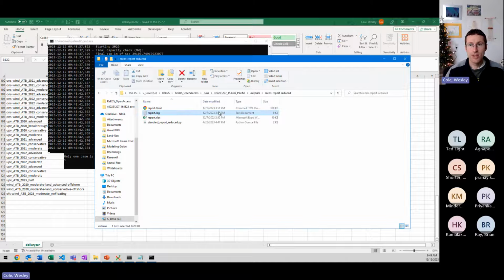Okay, so somebody's asking about running the ERCOT case, but importing and exporting from other states. That is not a feature currently in ReEDS. ReEDS doesn't have any capability to have exogenously specified imports or exports. ReEDS only knows about the regions that you're modeling. So in the specific test case, ReEDS only knows about that specific test case, and that's all. Like, California imports a lot from Nevada. California is in the Pacific test case, but Nevada's not in the Pacific test case. So there is no import or export from Nevada. There's no way to specify that currently.